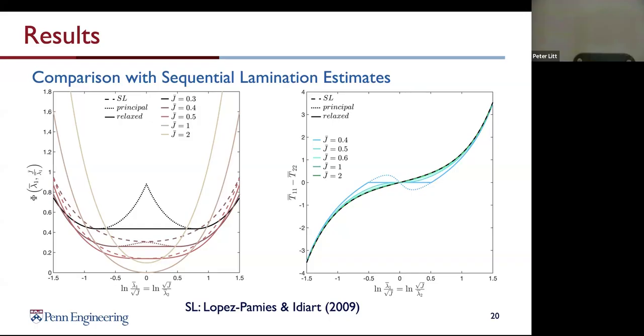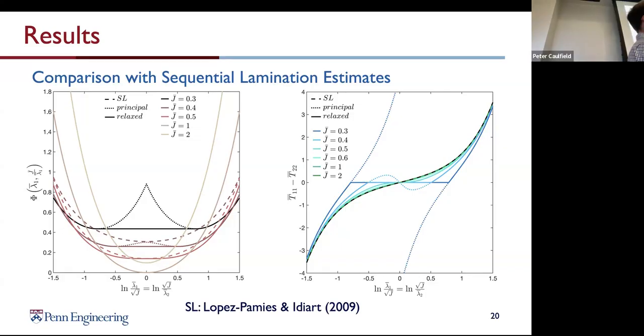The relaxation in this case corresponds to what we saw before, where you cut across that non-monotonicity and make it just flat there. It corresponds to that equal area construction, so the areas of both of these regions are the same. You can continue to compress and get something which is less well behaved, but again, you just cut right across the middle. An important thing to note here is that you have this line which is exactly at T11 minus T22 equals 0, meaning 0 shear stress in the material once you're in this relaxed regime, which is what you'd expect from the fact that it's behaving like an elastic fluid.